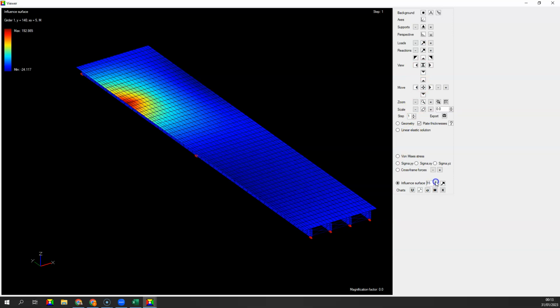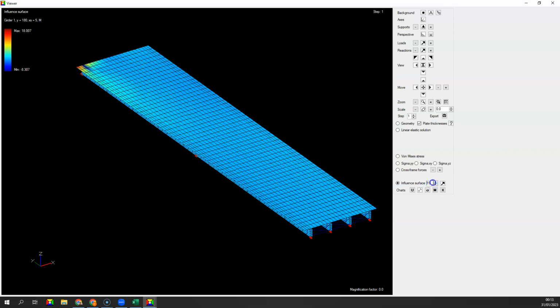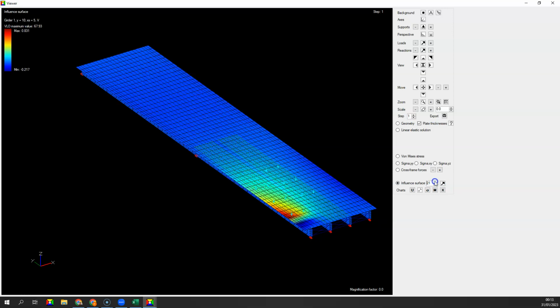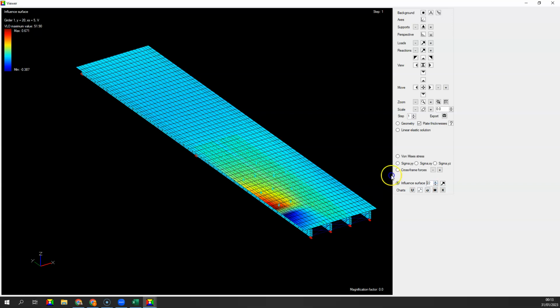We are getting to the end of girder 1, and now let's go to influence surface number 19, which is the last one. Now it will be about shear. So V here is for shear. Let's look at the critical load configuration. We have 2 lanes, and again we have kind of this wave here which is propagating.